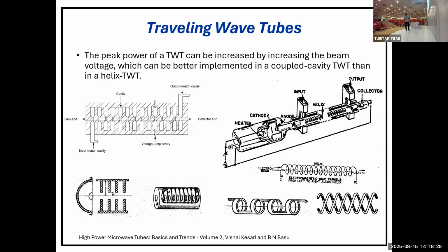So people had the idea of a coupled cavity traveling wave tube. It reduces the bandwidth. Whenever you hear cavity, it means there is a high Q. Whenever you have a high Q structure, you have small bandwidth. But you can generate really high power, megawatts or gigawatts, probably with gain from 20 to maybe 40 dB.